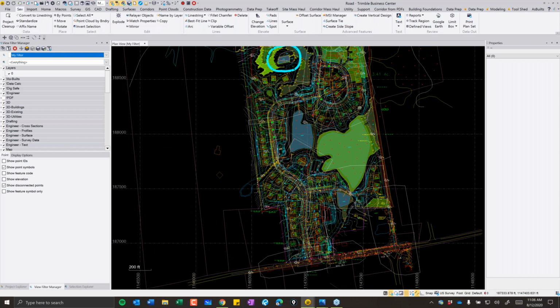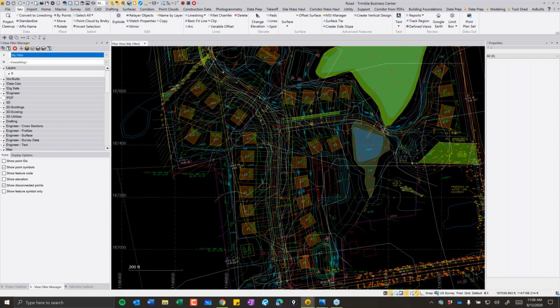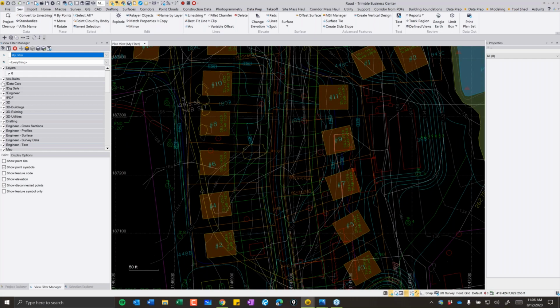drawing that we would receive from an engineer and go through the processes and highlight some of that. So I did very minor data prep for bringing this in, but one of the most important things that I find when bringing in a drawing is I like to use the suffix for the layers, and part of that is just to keep things organized, keeps that data, whether it's a revision or a small change, grouped together. So I always put engineer in front of those layers, and then usually I'll put the import date or the revision date. That just helps to keep your sanity.